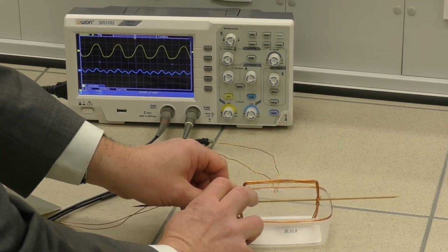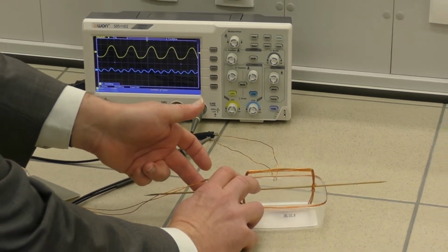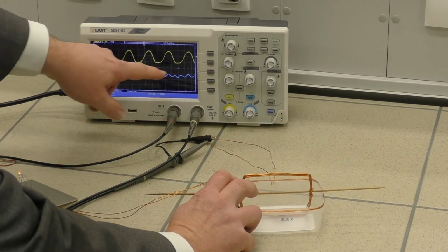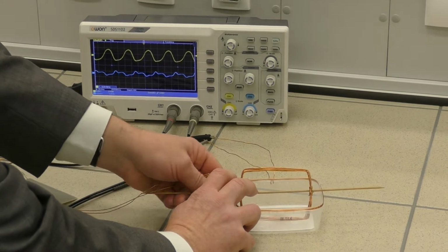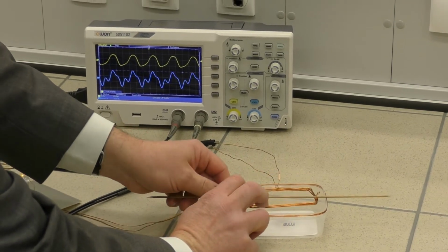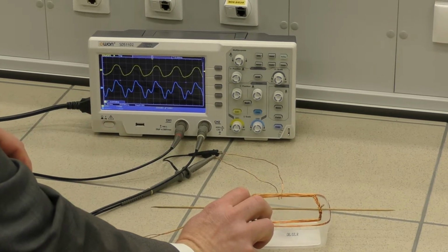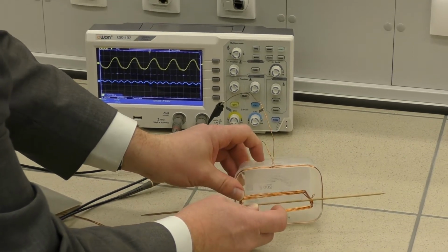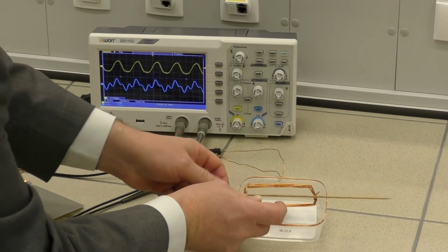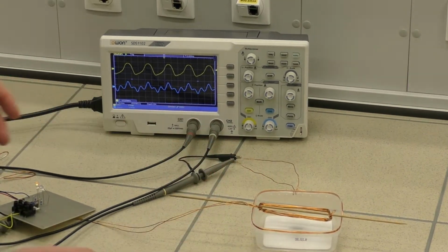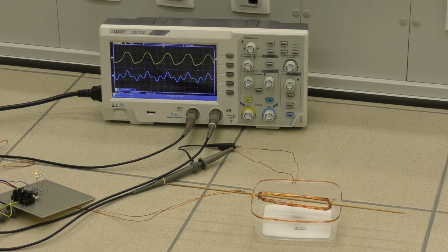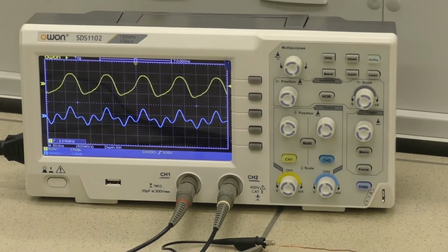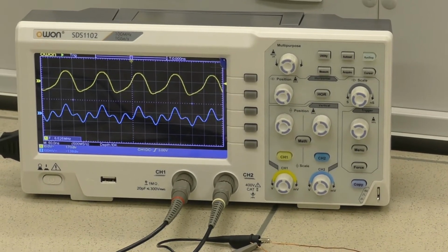In this case, it's just 90 degrees turned, so there is nearly no signal except the noise. So the dependency of the resulting signal on turning depends on the sine of the angle. For the second winding, it will be cosine. So the same principle is used for a resolver to measure the position of the rotor inside the two stator coils. We will show it on our real equipment in our laboratory.